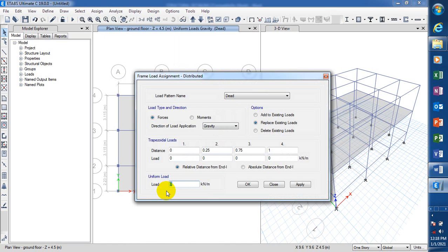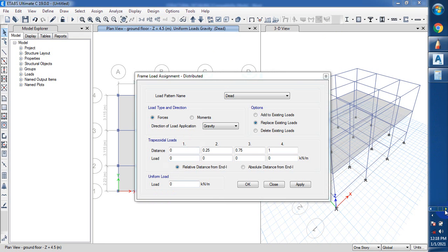At this point, my wall load is going to be the weight of your wall, which is 2.87 kilonewton per meter square. I have treated all of this on my structure software, which I explained vividly. That's 2.87 for the 9 inches block, that's 225. And then you know, you have an opening. Let's say we have an opening in that wall as well.